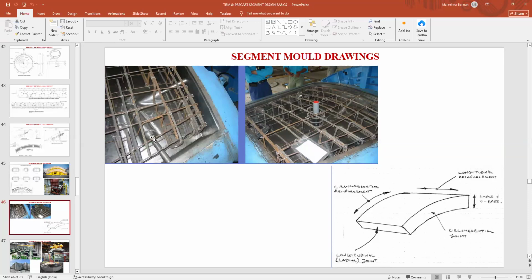Now, one big example was initially in Lucknow Metro, when they were doing the first phase of the TBM project. There we got a cover, I think, of less than 25 mm, because at the bolt pocket there is a codal specification that the bolt cover should be minimum 25 mm with a plastic sheet, that all your reinforcement should be encased in a plastic sheet. So here we got a cover of less than 20, it was around 17-18 mm.